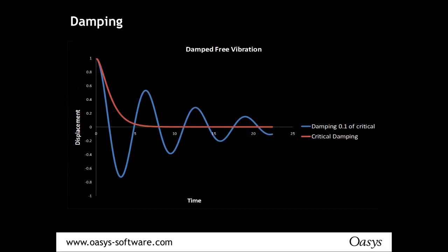Now, if this resonance was unchecked, it would just induce vibrations which would eventually destroy the structure. Yeah, the old Tacoma Narrows problem. Thankfully, real structures have inherent damping in them which absorbs the energy from these vibrations, and therefore we need to take this damping into account. You sometimes hear the expression critical damping. Now, critical damping is a quantity of damping in the system where any displacement immediately just reverts back to zero in the shortest possible time.